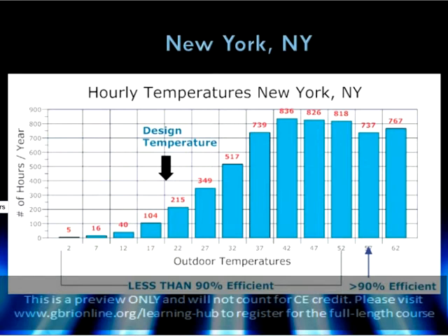So you're going to be paying more for a condensing boiler, which is typically 20 to 25% higher than a standard efficiency boiler. And if you're going to go to a reset like this, it's a waste. Your condensing boiler, your 90% efficient boiler, will not hit that condensing part until it gets up to 52 degrees.